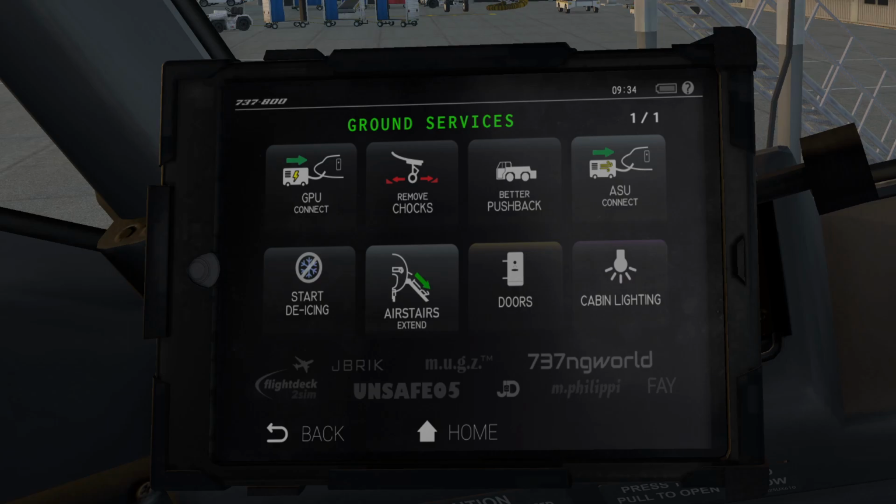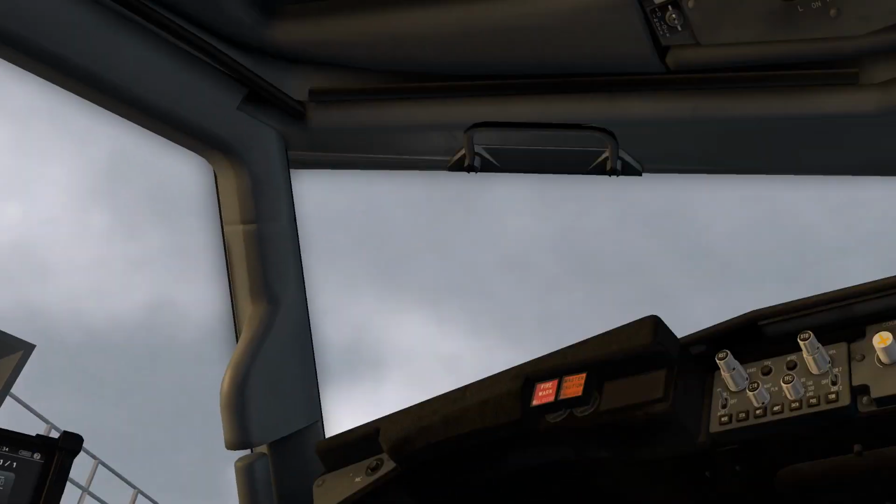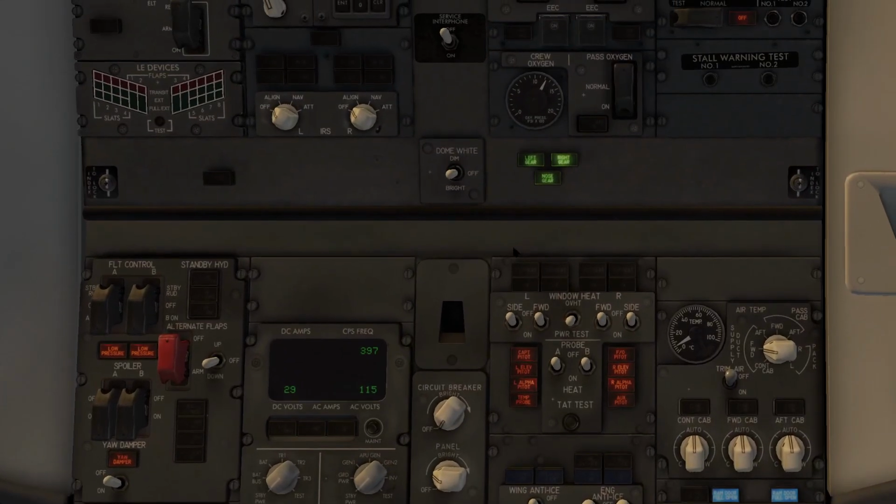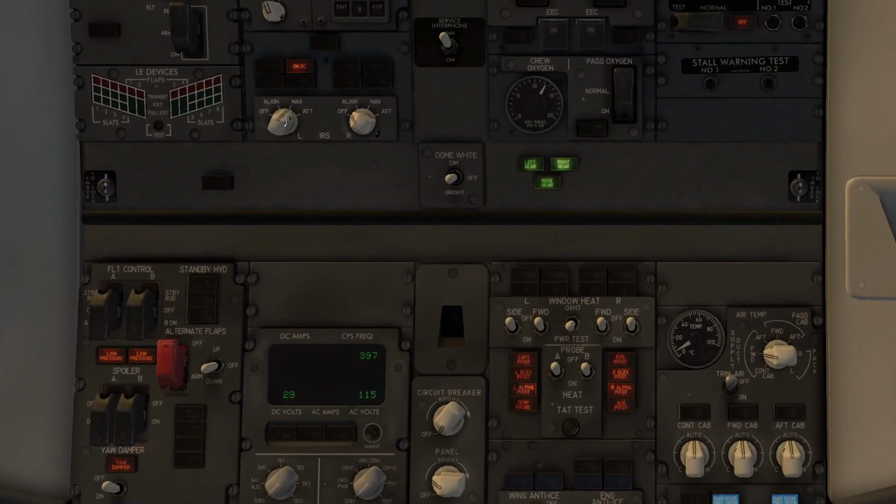Now we check how we can put that flight plan into the FMS. So first, battery on, we have ground power, so ground power on. Emergency lights on, and we align the IRS left and right. On DC, align light illuminates, on DC, and then align. Yaw damper can be preset to on.